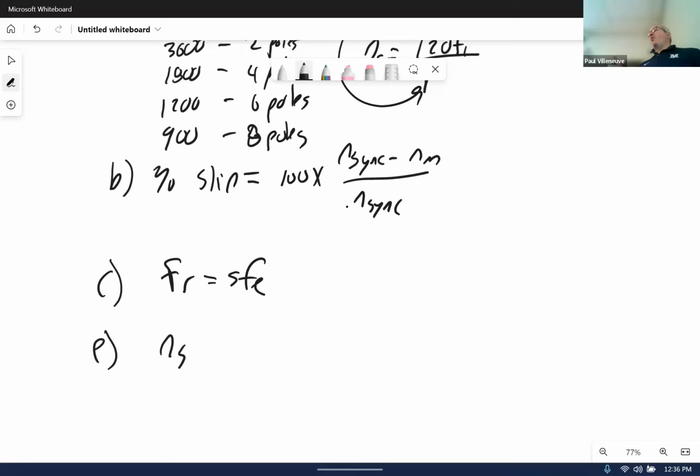So the frequency on the rotor, you can convert that to a synchronous speed, just like what we did on the stator. Remember how we took a 60 hertz three-phase set of windings? If you take the same thing and instead of running it at 60 hertz, run it at 1.8 hertz or whatever it is, you're going to get a rotational speed that's going to be the actual slip speed. So when you add the fact that the rotor is spinning at mechanical speed, plus the fact that you have three AC currents spinning around and creating a magnetic field, that's how the difference is made up. Those two speeds make up the difference.